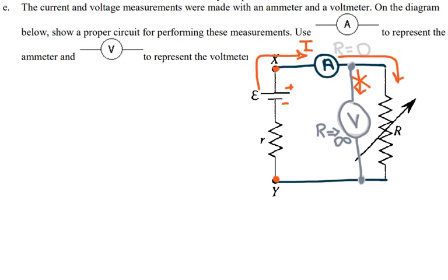And all you have to do is to know how to plug in voltmeter and ammeter. So ammeter always has to be plugged into the circuit. So if you see the line, you have to disconnect the line somewhere and plug in the circuit. So you see I disconnect right here, plug in ammeter, and then I continue my circuit. And then for voltmeter, it's always parallel to the, like, let's say if I want the resistance between these 2 points, the yellow ones, then I plug in my voltmeter parallel to that resistor where I want to measure the potential difference drop or the voltage drop.